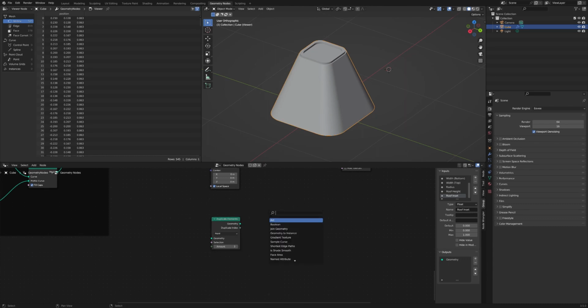And each of those different things we're going to set the position of. We're going to set the position of the first thing at kind of 0, 0, and then the next one's going to be a little bit higher, and the next one's going to be a little bit higher above that. And then what that will do is we'll create some steps that we can then use as booleans. So the way we can do that is we have our base geometry, which is just going to get fed straight into set position. And then we can use our duplicate index, which will go 0, 1, 2, 3, 4, depending on the number of things in that array.